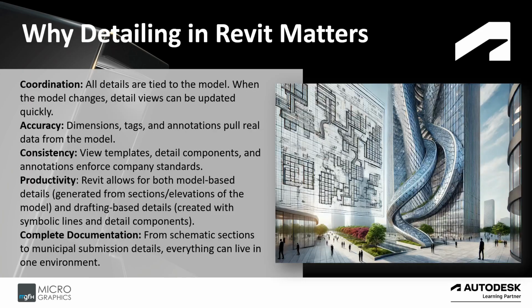So why does detailing matter in Revit? Coordination: all details are tied to the model. When the model changes, detail views can be updated quickly. For accuracy, we have dimensions, tags, and annotations that pull real data from the model.